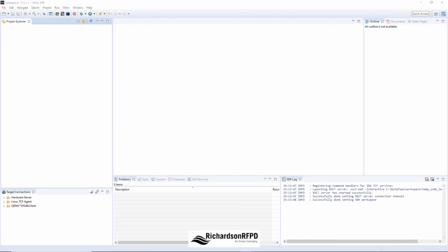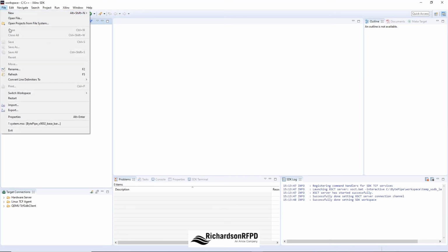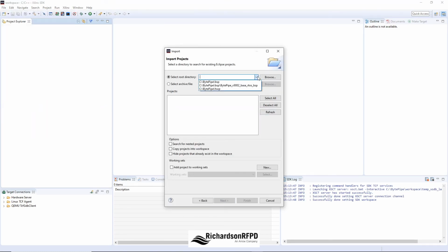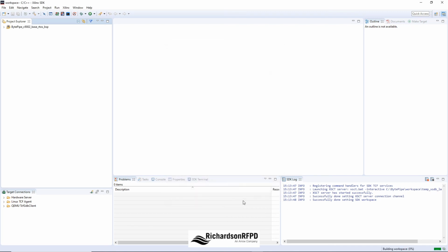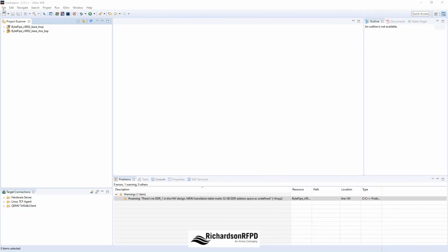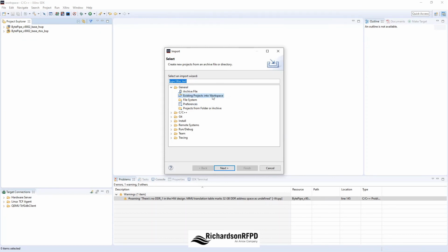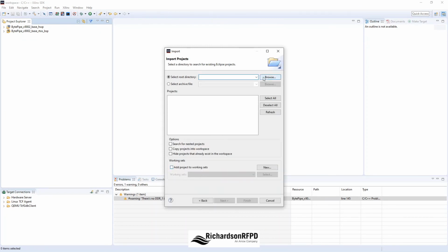The user can decide to create custom hardware platforms and board support packages, or use pre-built examples provided by NextGen RF Design. Here we are importing an existing BSP into the workspace. This BSP uses a real-time operating system. Next, we are going to import a simple NGRF CLI application that configures the ADRV9002 and allows for the user to control from a command line interface.